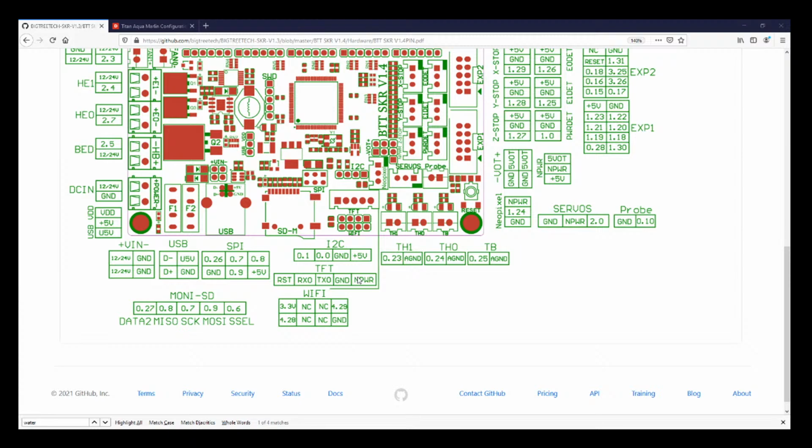Sorry, it just takes a while for me to get this into the right place. I know you probably can't see the multimeter that well, but I don't have a lot of space to show you. So it looks like the cable's working. So the only question is, why are we not getting 5 volts to the actual board? And that question is probably relevant to the tracings.